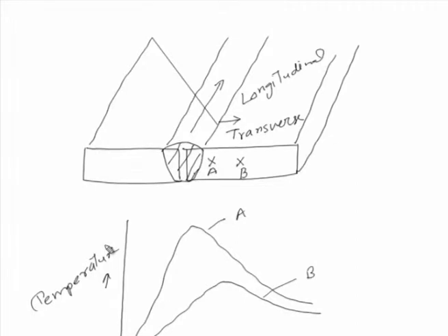If more heat is supplied for melting the faying surfaces and a lot of weld metal is deposited, then subsequently on contraction this results in a huge magnitude of residual stresses in the weld joint. So, in order to avoid that possibility, efforts are always made to deposit the weld metal as little in quantity as possible, and with as little heat as possible.